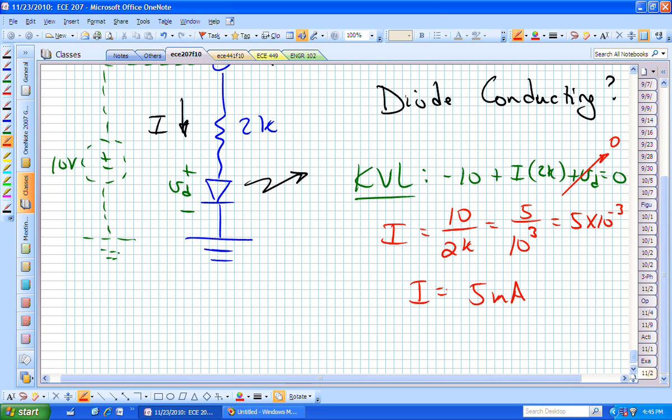You take it home and you go, oh, I can barely see it. It's barely lit. It's not burning very brightly. You go, it should have been 10 milliamps to make it brighter. Oh, what do I do? Get a smaller resistor.